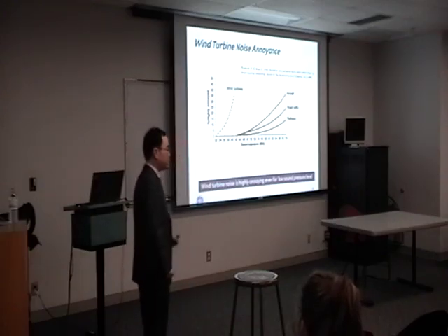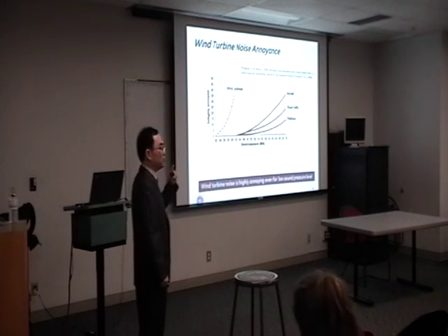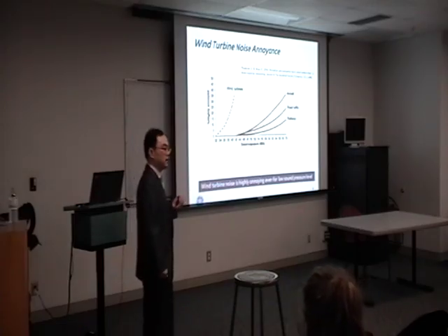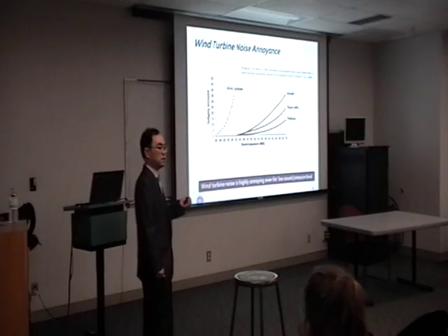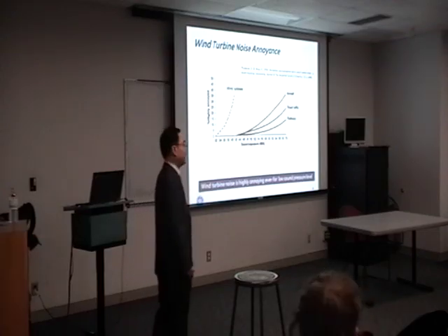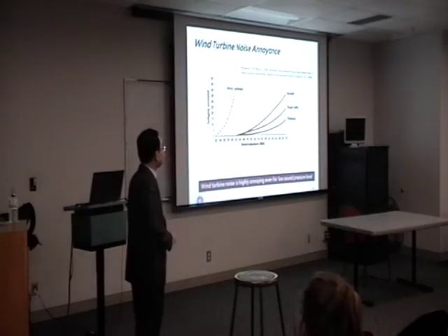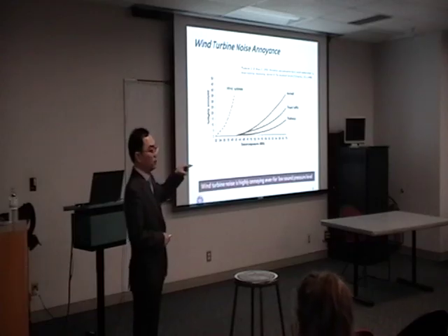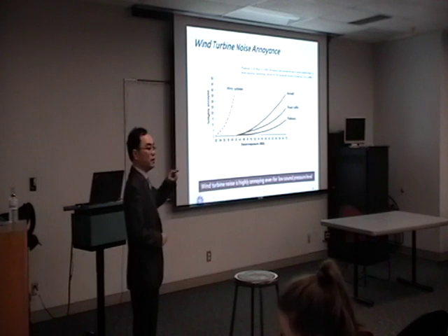It's because it's constant and it's related to the motion of the blade. When it rotates, it causes very annoying noise. It's a swish, swish, swish, swish. It's constant. So people complain. The aircraft noise and traffic noise in railways does not have that kind of large fluctuation, but wind turbine noise is a fluctuation. If you get the average intensity value, it's not that large. But if you hear the noise variation, it's really annoying.